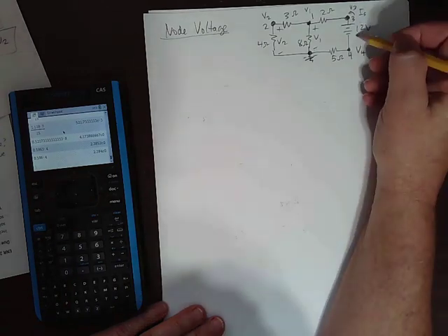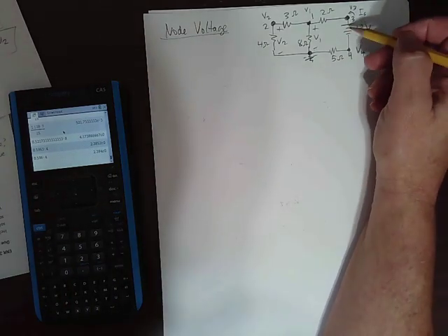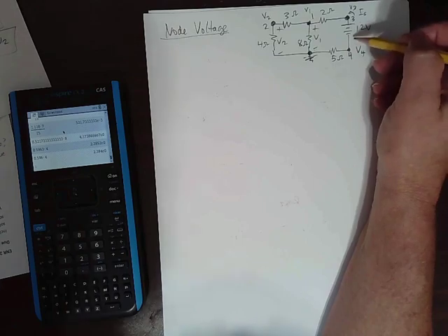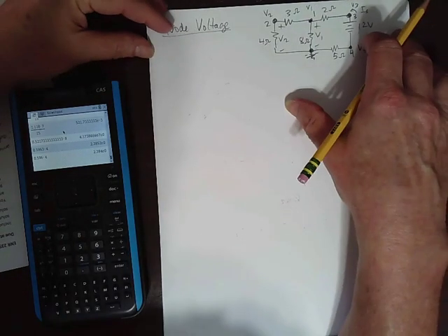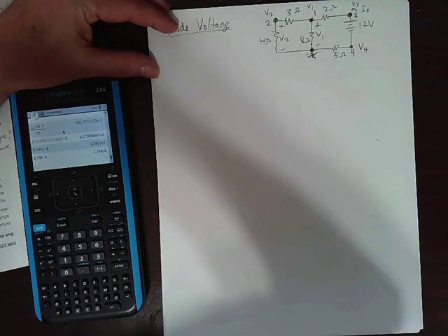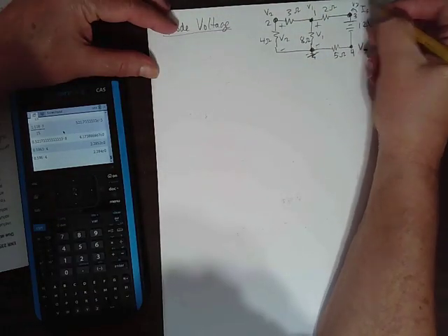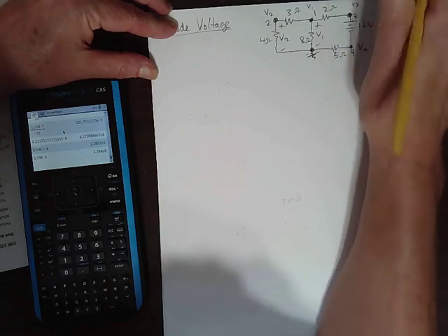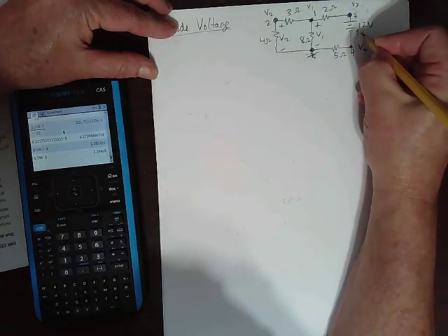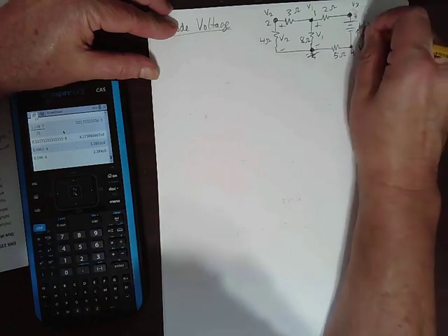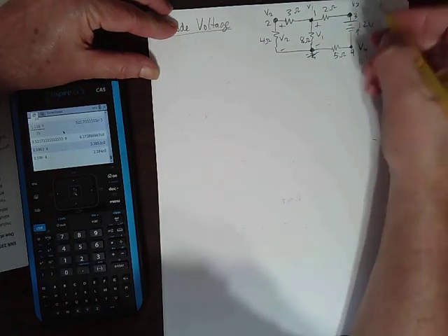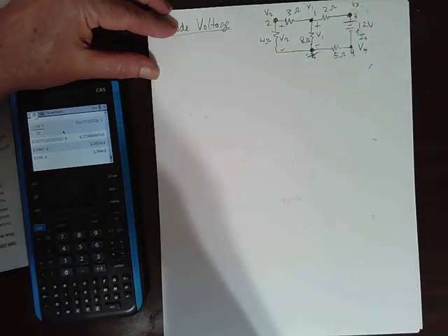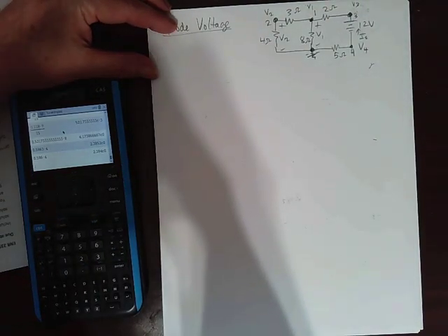So, we know the voltage of this node, but we don't know the current in this source, right? The source is going to hold the voltage whatever it needs to be, and so we don't really know the current there. This IS is kind of getting lost in here. We can write the current as IS, but again, that adds another unknown in the circuit. So we will do what we call a supernode around that voltage source, but we will figure it out.